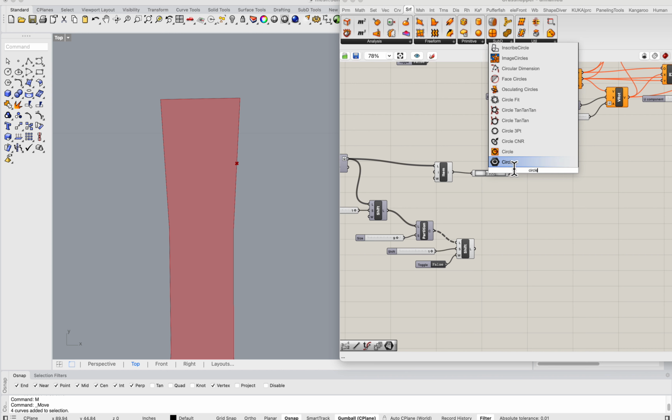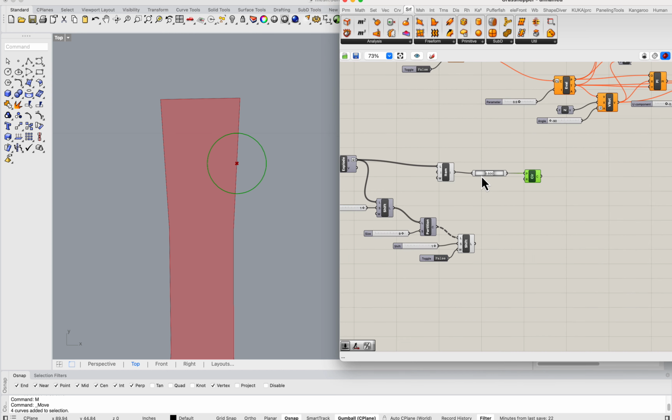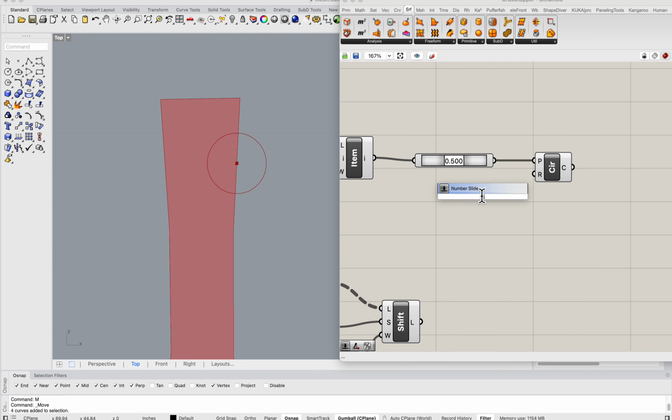and do a circle. So the circle size dimension is dependent on the type of bolt and nut you want to use. If you're using light material, you want the bolts and nuts to be small so that they don't put extra weight on the construction. Another option is to use rivets, but again, they're metal, so they will be adding more weight to this construction. So you might want to be a bit more precise. If you can find plastic connectors, that could also be another alternative to use for these sorts of projects.